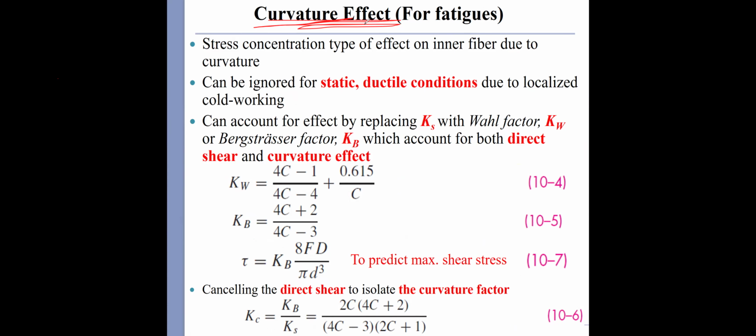So we have to take into account the other factors, KB or KW, for the direct shear and the curvature effect, named after these two scientists. Either way, you can use KW or KB, and in this course we're going to use only KB. Of course, you can use KW, that's no problem.